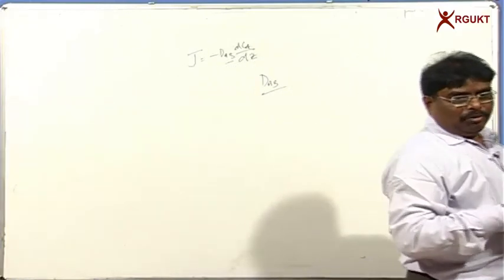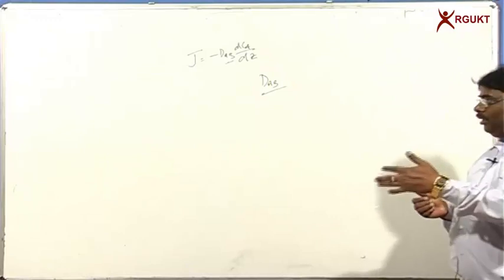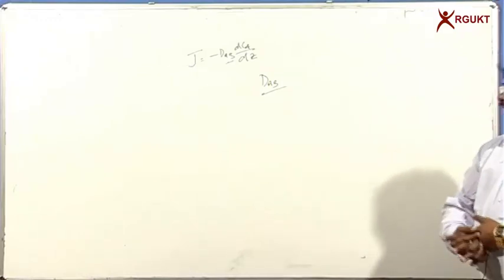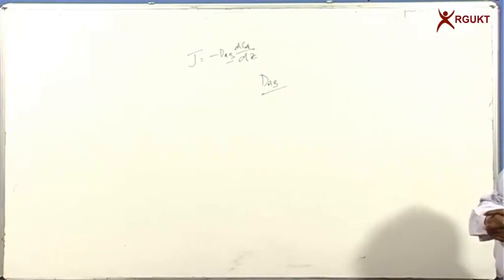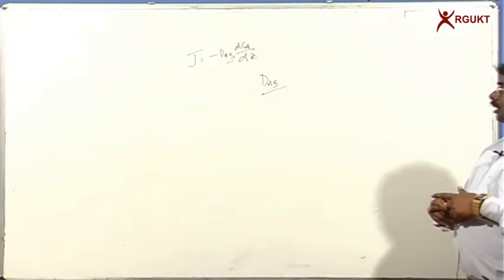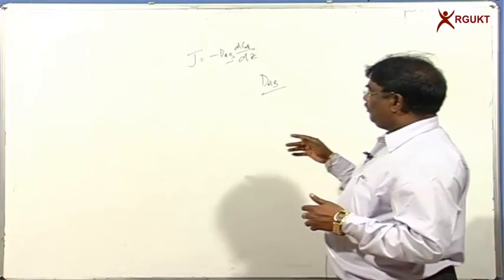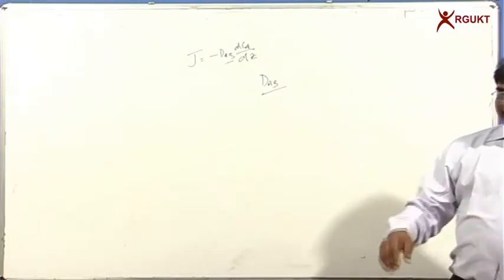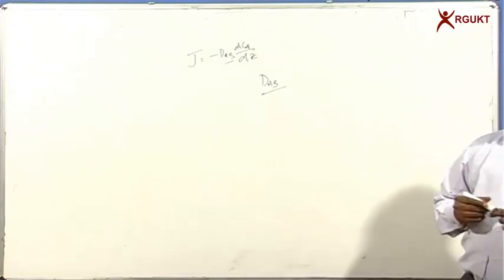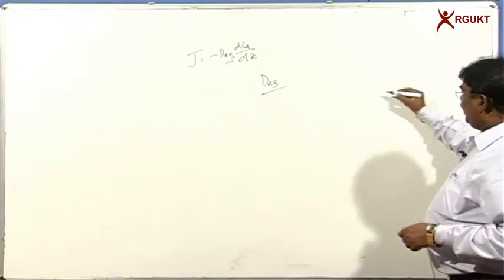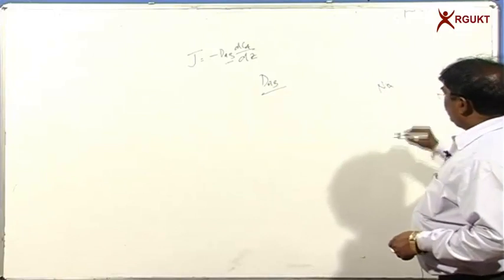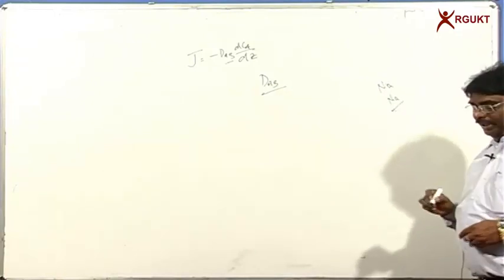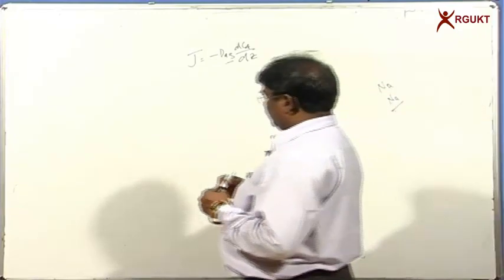If 1 mole of A is moving in one direction, 1 mole of B is moving in the opposite direction, then Na is equal to minus Nb, so Na by Na plus Nb is equal to 0. We tried to derive an expression for the calculation of Na for the equimolar quantity diffusion, and also the equation for the calculation of Na for the non-diffusing B case.